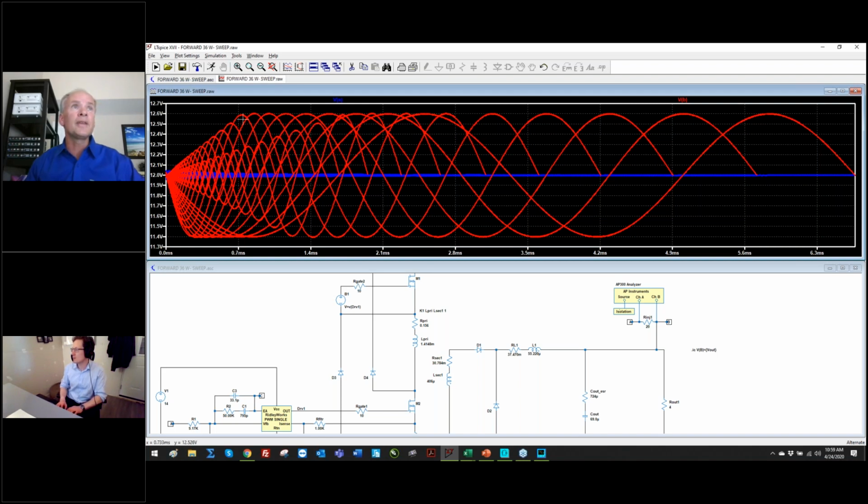Okay, so running these sweeps on a simulation circuit is just like running them in the lab. If you don't set up your analyzer properly, you get garbage in, garbage out. If you overdrive, it distorts. If you underdrive, you can't read the results. So you have to shape that injected curve as you go. All of that is automated with that Psim link here.